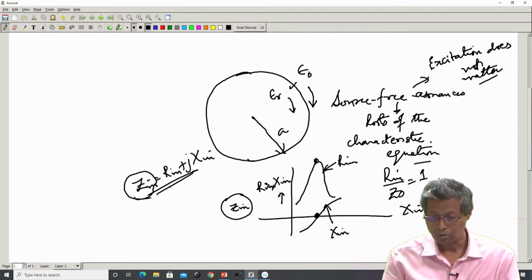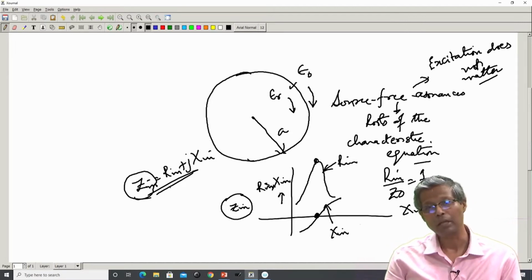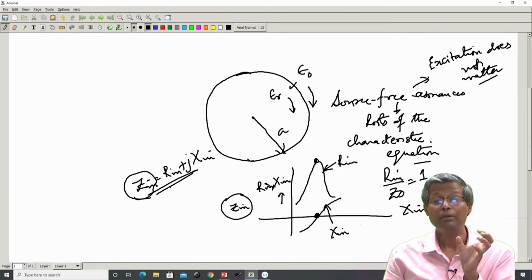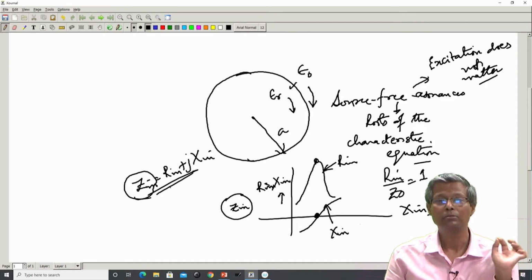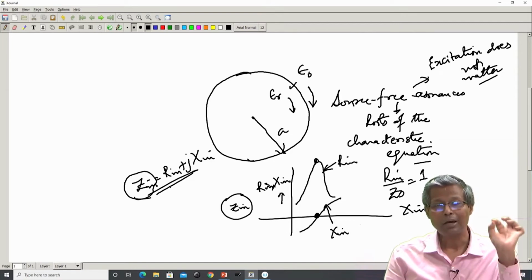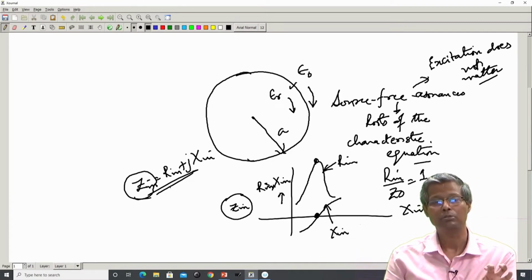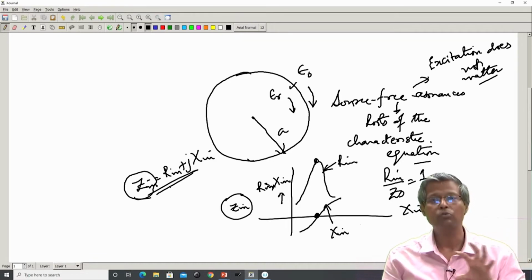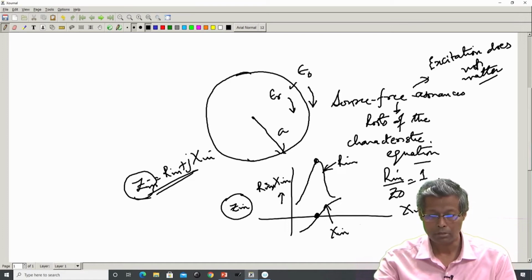So, it evaluates Z in taking into account the presence of the excitation source, and that is called the loaded resonance. The source free resonance is as important as the loaded resonance, because the source free resonance gives me the information as to which mode is close to the S11 dip. So, for the dip in S11 corresponding to the matching condition, which mode is principally contributing to that resonance? This information is provided by the source free resonance. That is why we search the source free resonances near a particular loaded resonance.